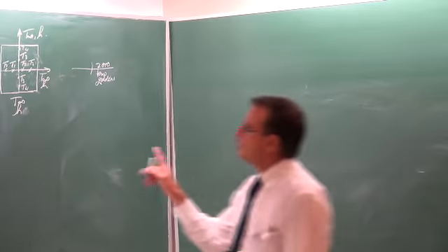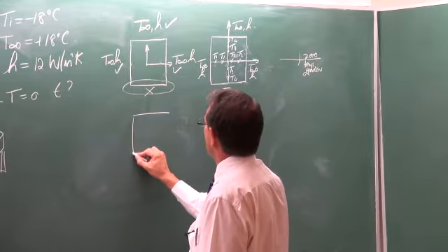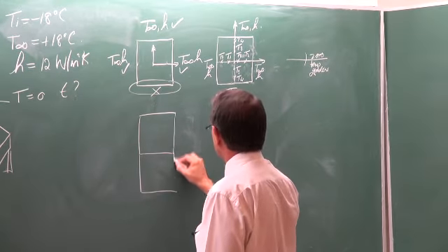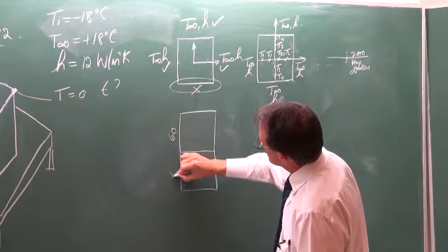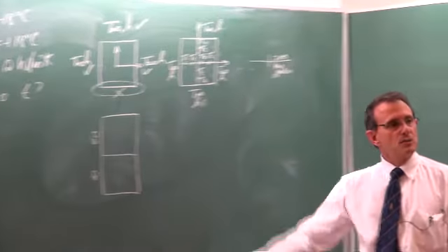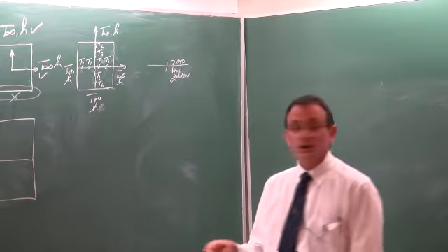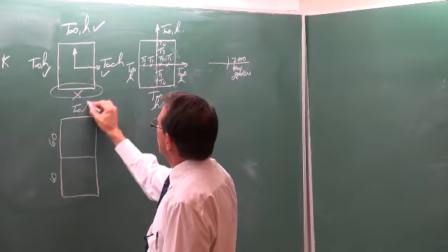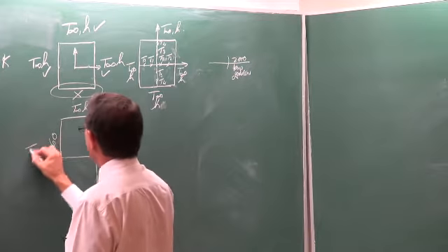Okay. So how can we fix it? We can fix this problem by saying, well, let's take this block as it is and we double its length. So where it is 60 millimeters, we consider the problem as if it is 120 millimeters long. If that is the case, then we put that boundary condition on all 4 the sides.